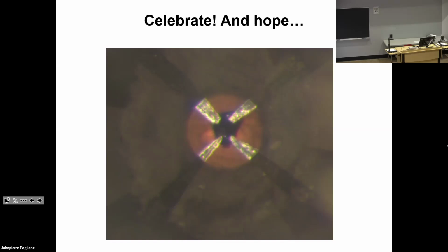I see. So the cubic boron nitride epoxy matrix is the most customizable way that I've found, but maybe you're looking for something that wouldn't have that underlying steel. I don't have a great sense other than if you find a non-magnetic steel or something like that. I don't know if anyone else has any other suggestions.